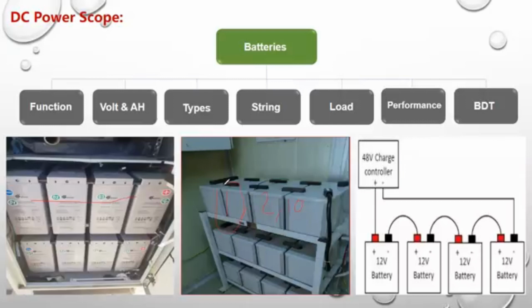So again, this dust will turn into mud and will close the battery pores. So it's better to dry dust with a blower or piece of cloth, as we mentioned, instead of using water first, as the dust will turn into mud and will close the battery pores.